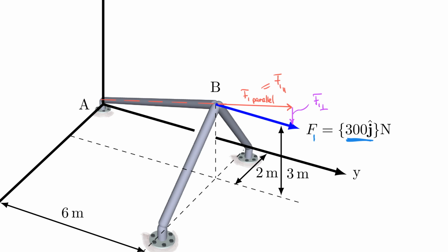So that is a concept that needs to be really visualized by engineering students. They need to understand that a force that is not acting parallel to a member always produces 2 components. It produces a force component that is parallel and one that is perpendicular. Let's not really worry about the perpendicular one right now. I know that often students get confused about this initially, but we will talk about this later, and actually we'll talk more about this in follow-up classes.